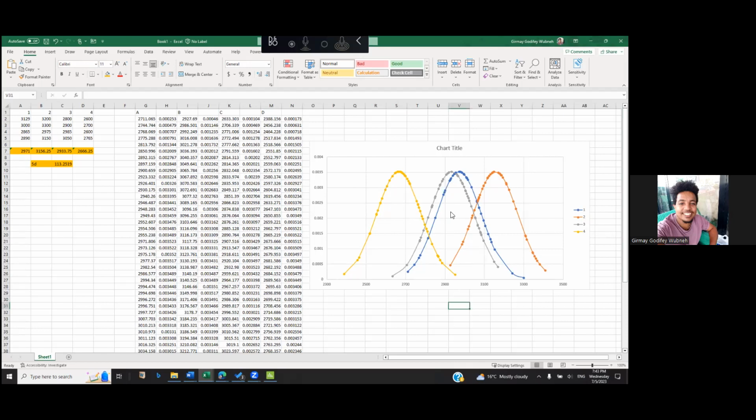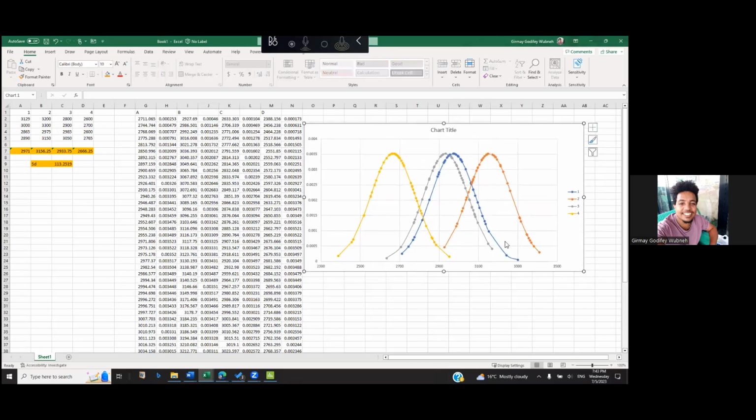So from this we see that mixing design 1 and 3 are similar, more or less the same mean, around here. So from this plot we conclude that mixing designs 1 and 3 have similar tensile strength, while mixing designs 2 and 4 differ from all the others.